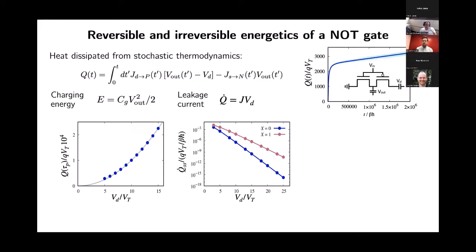I kind of naively expected that if I increase this driving voltage V_D, I would have correspondingly got a larger entropy production, as you might expect from the equation I've written here, that the entropy production is proportional to V_D. But this comes with an offsetting factor that as I increase that drain voltage, I actually suppress the currents that flow. This is a consequence of the overlapping Fermi functions that become out of resonance as the voltage becomes very large.